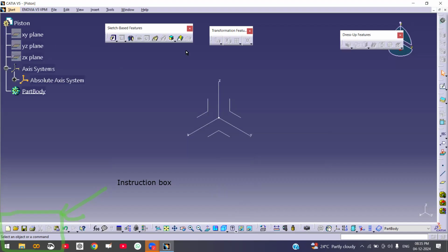So now from entering into 2D to 3D. For that, we use this command, sketcher. I drag this and drop. Here you will have two options. One is sketch, one is positioned sketch. According to the industrial standards, they use positioned sketch. They don't use normal sketch. I'll tell you the reason, the difference between positioned sketch and normal sketch.